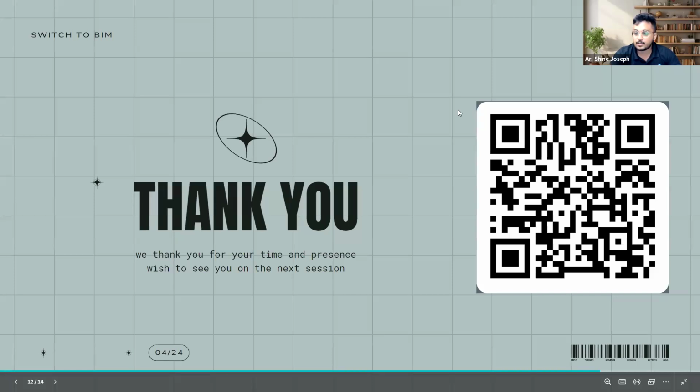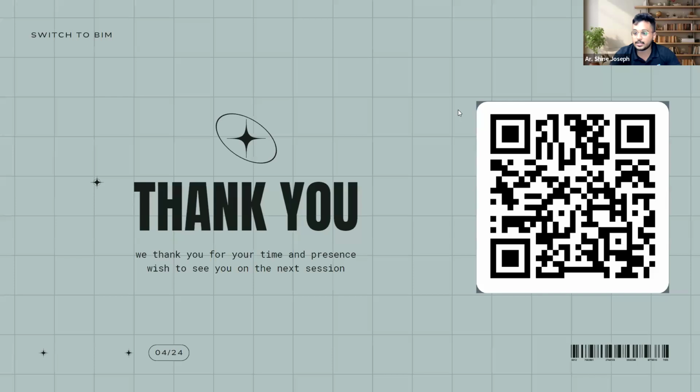Next question from Rohit. Can bill of quantities be generated? Yes. That was the last part that we were showing, the schedule part of it. From the schedule, in the same way, you just add these properties such as getting how many tiles or bricks, you can do that. This property will let you use the equation. You can have a set of properties of prices. If you add a price such as the cost of one brick or cost of one tile as a property, you'll be able to create the price as well within the Archicad software. You have the option to export it as an Excel file and work with it, but Archicad also lets you work within it using this property manager.